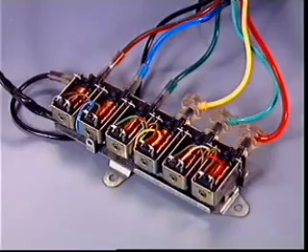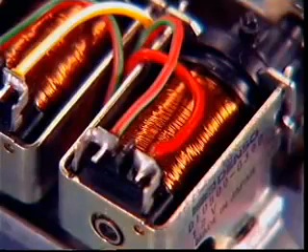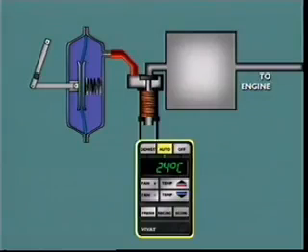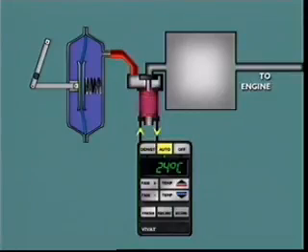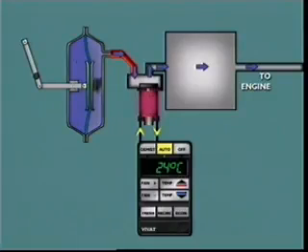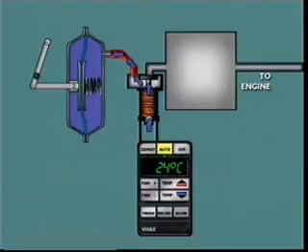The vacuum delivered to the diaphragm chamber can be controlled by a solenoid valve. When the electronic control unit wants to move a damper flap, it grounds the electrical circuit for the solenoid winding. Vacuum from a storage tank is applied through the solenoid valve to the diaphragm. To release the diaphragm, the electronic control unit open circuits the solenoid, and the diaphragm returns to the rest position.